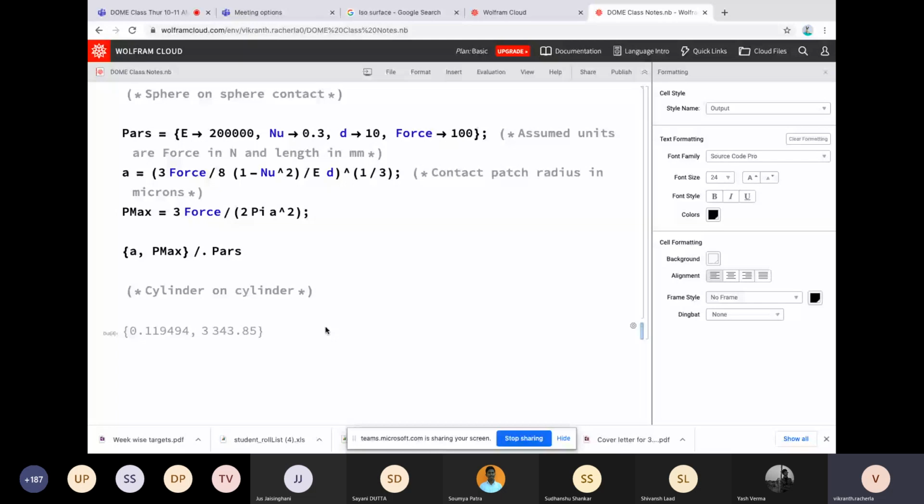It is so little that basically the force is getting applied on a very small area, and consequently the contact pressure is very high. Okay, so this is a feature of contact, that because steel and metals in general are very rigid, the area across which the contact patch forms is normally very small, particularly for non-conformal contact.